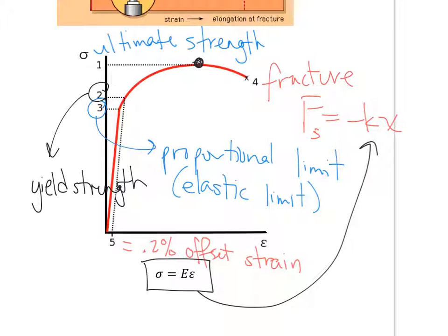Let's look at another thing. Let's look at Kevlar. Take a look, please. Look at the stress strain plot. Stretching very lightly, following Hooke's law. It's going to start to curl down. This is the Kevlar specimen itself. I'm pretty sure that this fails abruptly. It doesn't stretch much at all. It is not very malleable. Kevlar is very strong, we know that.